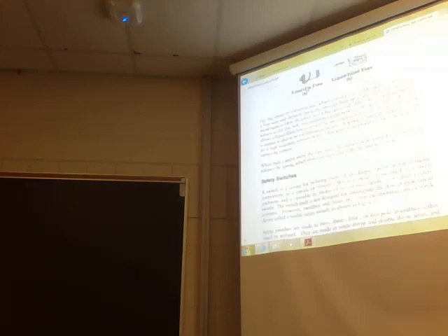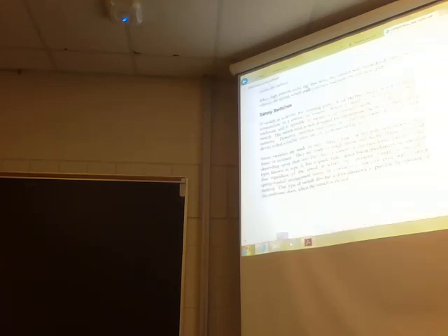A safety switch is a device for isolating parts of an electric circuit or for changing connections in a circuit or system. When a switch is mounted in a metal enclosure and is operable by means of an external handle, this is called a safety switch. The switch itself is not designed for interrupting the flow of short circuit currents. However, switches and fuses are often incorporated into a single device called a fusible safety switch,